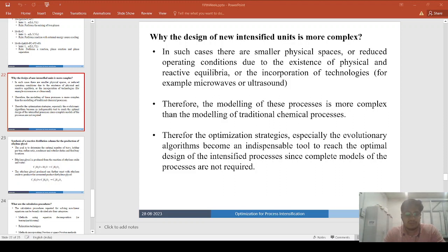Now, in the case of reactive distillation, both conventional and thermally coupled, for the production of biodiesel, a multi-objective genetic algorithm with constraint handling can be employed in order to generate the Pareto front. Now, for the optimization of a transesterification reactive distillation column with thermal coupling, the elitist non-dominated sorting genetic algorithm of the second generation can be employed along with the HYSYS process simulator.